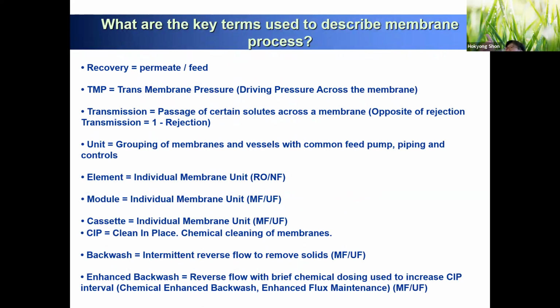You desalinate the seawater at 50%. So you have 0.5 liter of drinking water, permeate water, and 0.5 liter of brine, high salt water. So you need to design recovery, because recovery is related to your osmotic pressure, your design of the applied pressure, and how you can calculate this recovery.